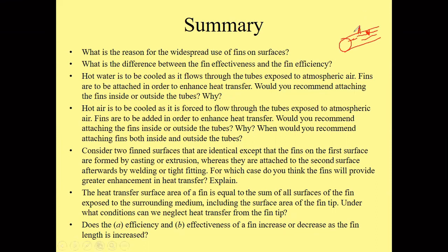So you know that fin effectiveness will be higher if you apply it to gas instead of liquid, because the gas outside here, the ambient, has a lower convection heat transfer coefficient compared to the liquid here, because there is flow inside.